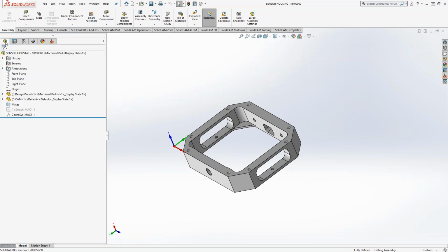If I click on this guy, we can see in our SolidCAM external, we have the design model, like we talked about earlier this week. This is the solid you bring in on the front end of your SolidCAM. So you open up a SolidWorks part, go to Tools, SolidCAM New, or you go to the side menu, and you click on New. However you get into your SolidCAM, the model that comes in the front end is the one that's going to be associative. That's the one that if there are any rev changes, your copy of it will get updated to match the revision version that you're on the design side of things. So that is the fully associated part.